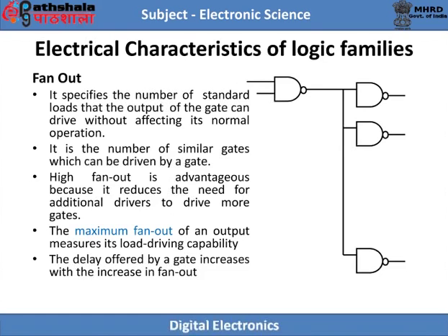The output of the gate is usually connected to the inputs of similar gates. Each input consumes a certain amount of power from the gate, so each additional connection adds to the load on the gate. These loading rules are listed for a family of standard digital circuits. The rules specify the maximum amount of loading allowed for each output in the circuit. Exceeding the specified maximum load may cause a malfunction because the circuit cannot supply the power demanded from it.